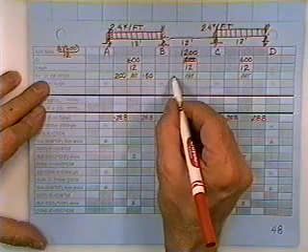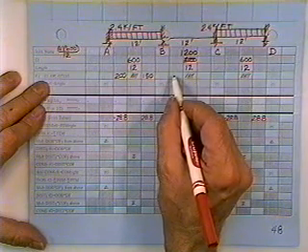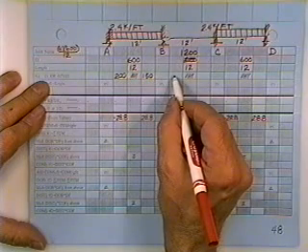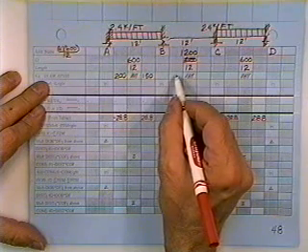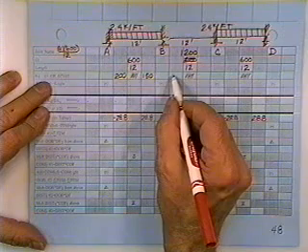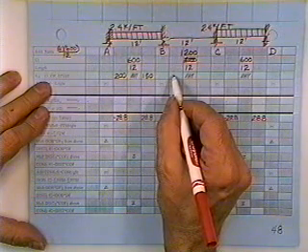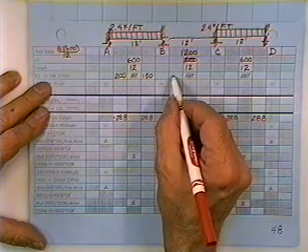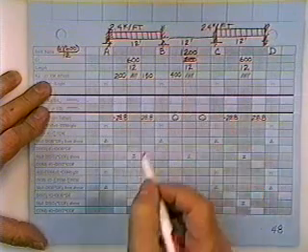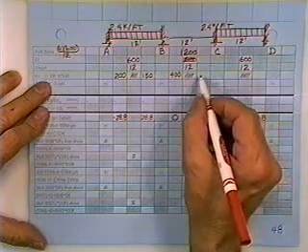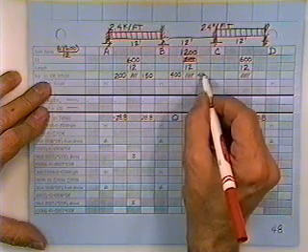Now I fill in the hole just to the right of joint B. As I stand at B and look to C, I see the beam continues on. It's not pinned and quits. Therefore, it's 4EI over L. 4 times EI, 1200, divided by L, which is 12. That number is 400. And looking back, I get the same 4EI over L, so that's 400.